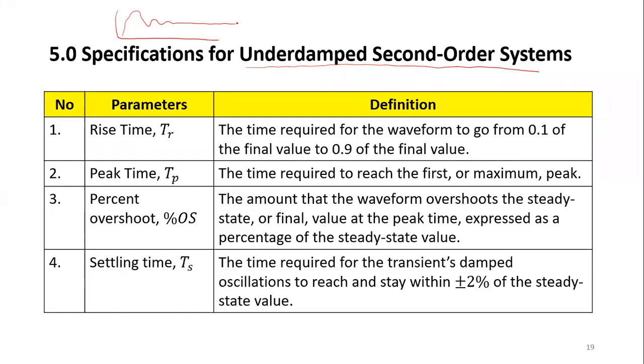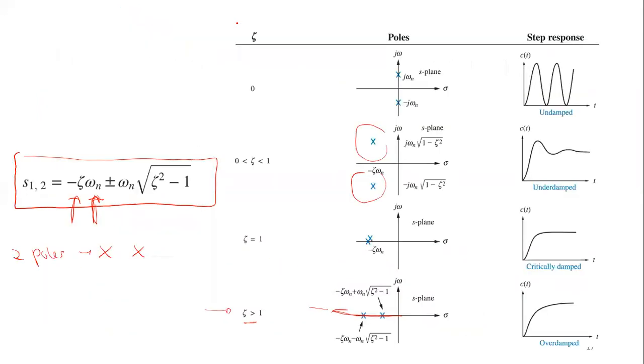It is impossible to get the antenna to move and give a response like a critically damped system. It's very impossible because of the gears and the environment. And of course, we don't want the antenna to have an undamped system. Usually, the normal response will be underdamped.